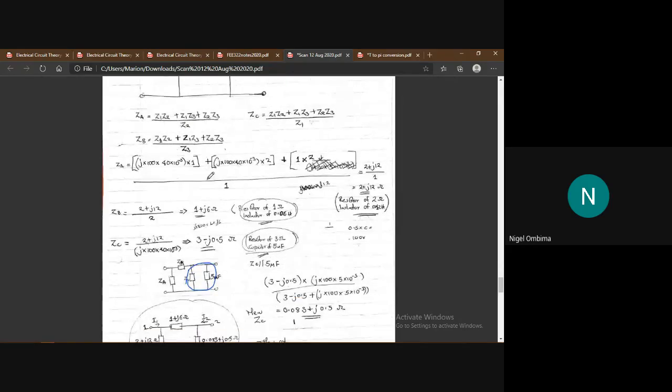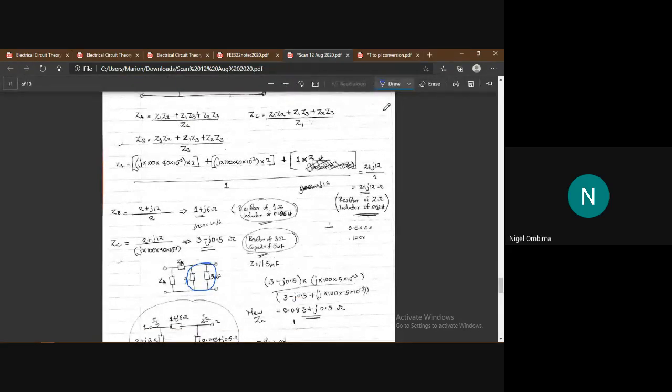So ZA is equal to Z12 here. So it's the impedances. So j omega, which is 100 times 40 millihenry, times 1, which is Z2. I just filled them out, changed this one into an impedance, into an impedance, into an impedance. I filled them in here. We calculate with a calculator. Okay, input into the calculator, it gives you this.